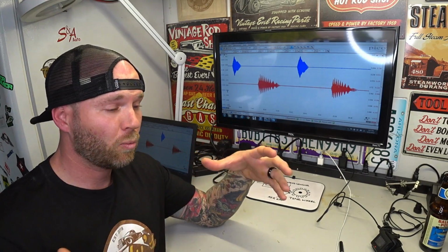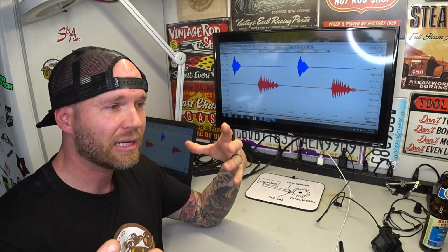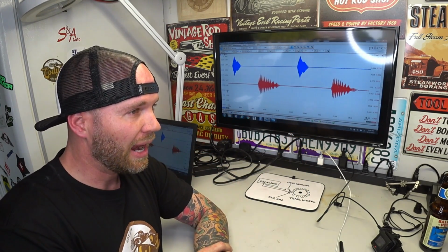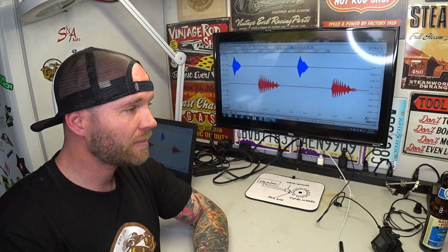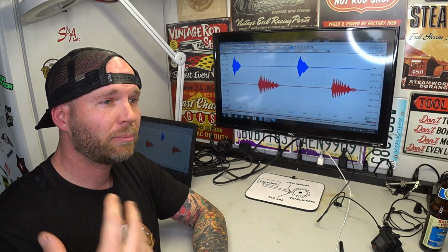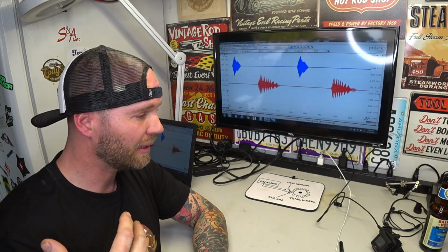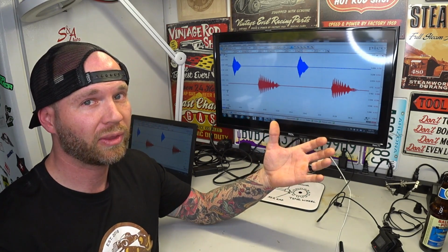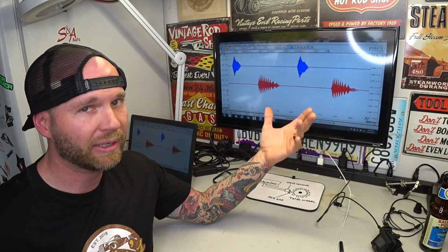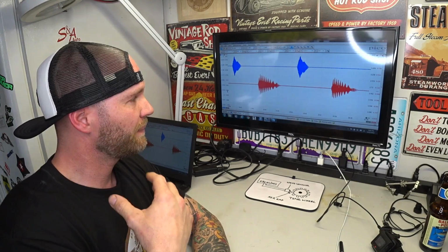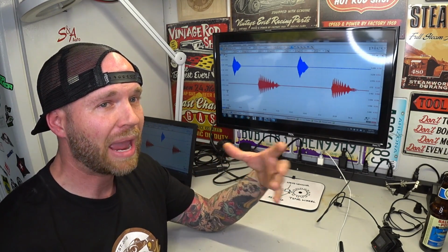Now, what we read on our scan tool is backdoor information, and that backdoor information is information that's interpreted by the electronic brake control module, or any module for that matter, ECM, PCM, BCM, I mean any kind of module, right? Using the scan tool, that's backdoor information.